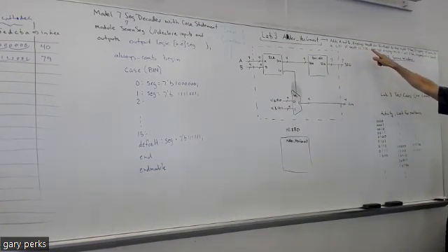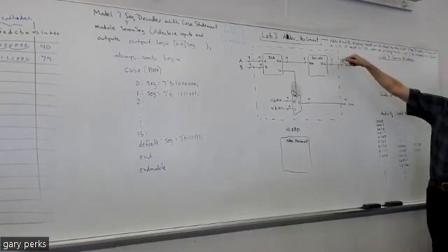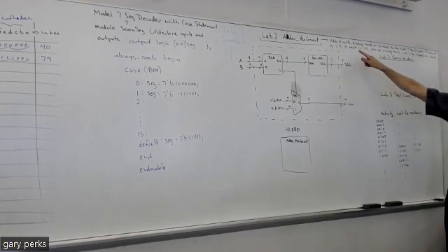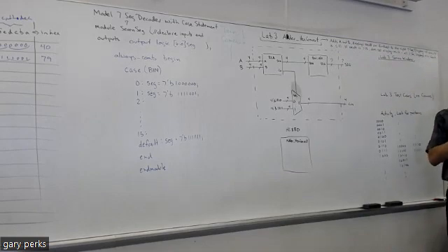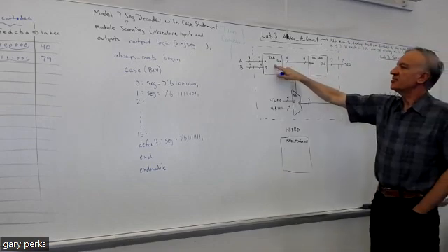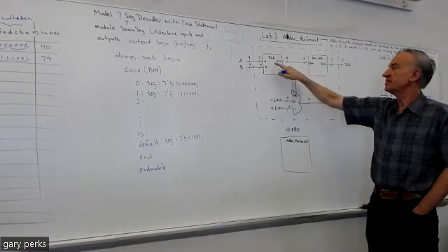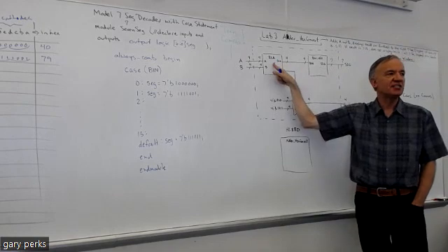But it adds A and B and displays the result on the furthest to the right 7-segment display if the result is less than or equal to 15. If the result is greater than 15, it does not display the result, and all 7-segment displays are blank. They're all off. Okay, so you got an RCA, and that's the same RCA that you built in lab 2, right?